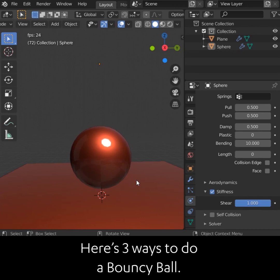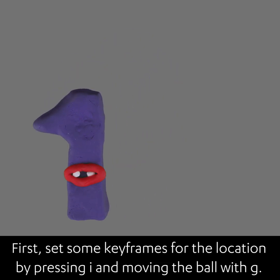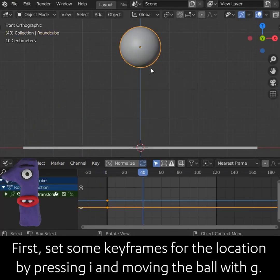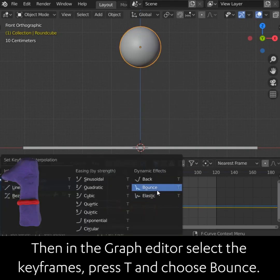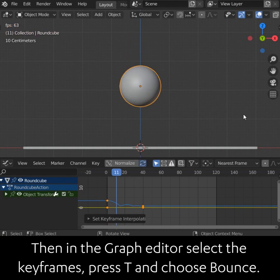Here's 3 ways to do a bouncy ball. Method 1. First, set some keyframes for the location by pressing I and moving the ball with G. Then in the graph editor, select the keyframes, press T and choose Bounce.